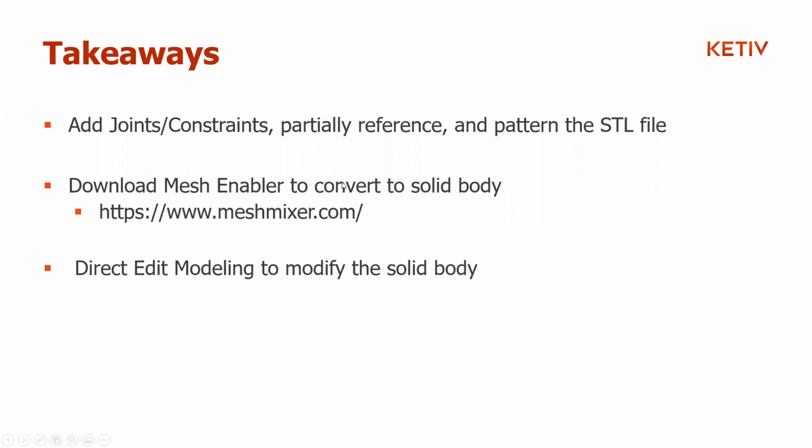And it's an older tool, but you can... Oh, sorry, this is confused, or this is mixed up. The Mesh Mixer is for the rabbit, the tool you saw there at the end. The Mesh Enabler is the add-in that is used to convert it from an STL file inside of Inventor to a solid body. So I put those in the same line. Those are supposed to be separate there.